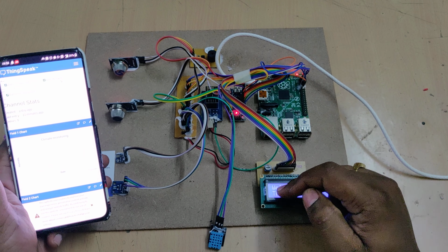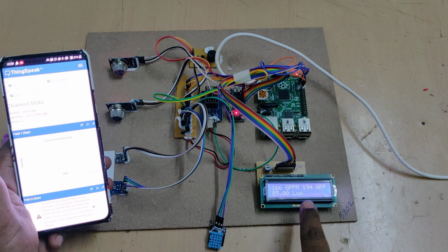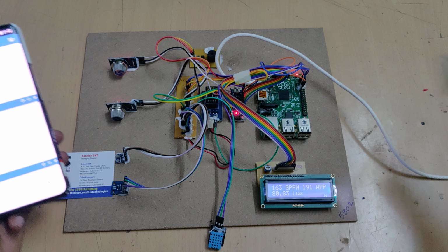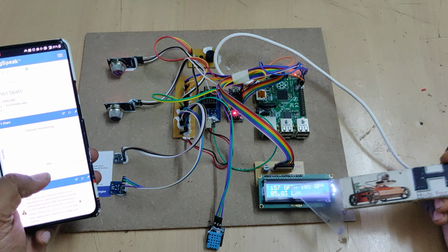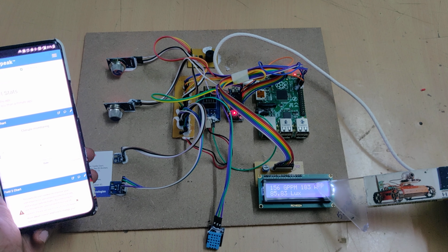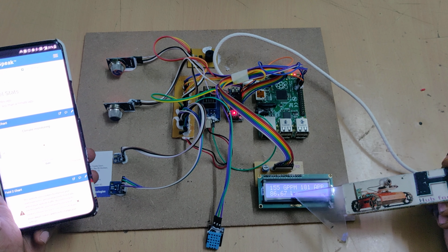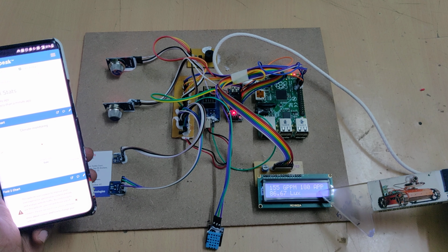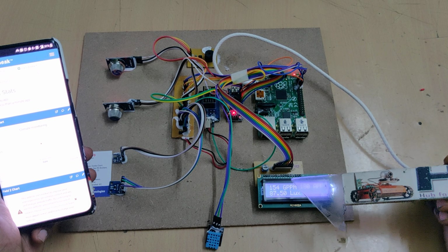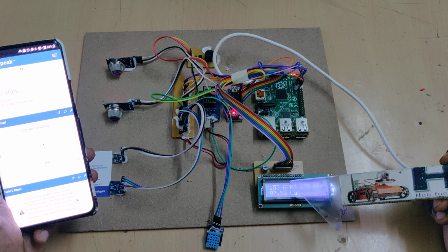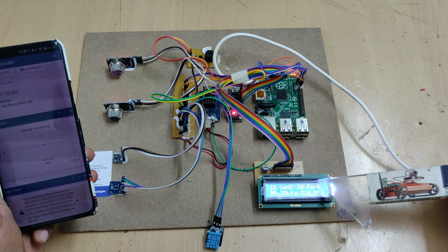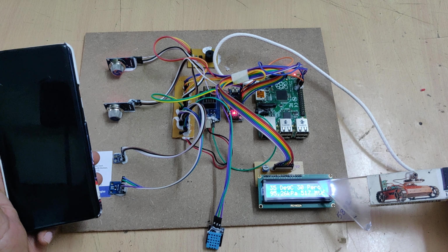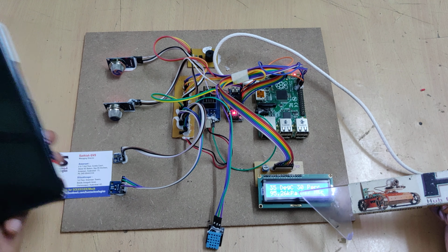and after that welcome message will be displayed on the LCD screen, and continuously the sensors data displayed on the LCD. Let me explain that. First one is degree centigrade, that is the temperature, and the next one is percentage, the humidity percentage, and next kilopascals, pressure, and next meters, that's the altitude, and next screen is 154 GPPM, nothing but gas parts per million, and 177 APPM, nothing but the air quality in ppm, and lux, nothing but light intensity.